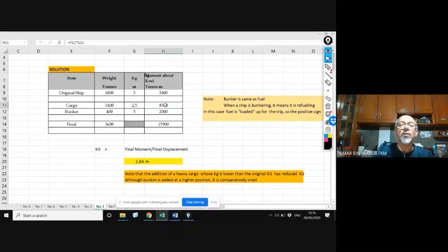So this moment, we should reduce the center of gravity, it is better. For a ship, always a lower center of gravity is better because Km is constant. Okay, so if you have a lower center of gravity like this one, then you have bigger GM. Always we want to have big GM. The spacing between Kg and Km is GM. So if you have low Kg, then you have better stability.